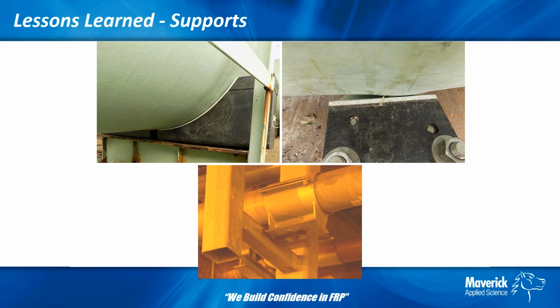Ideally, in the design phase, you would like to see the engineers identifying the locations of the supports and the locations of the joints so that the joints did not interfere with the support. So you want the joints a couple of feet away, something like that. It doesn't have to be substantial, but just not in the same place, because you don't want to put a point load at a joint, which is a point of greatest concern, where generally the pipe's not going to fail.